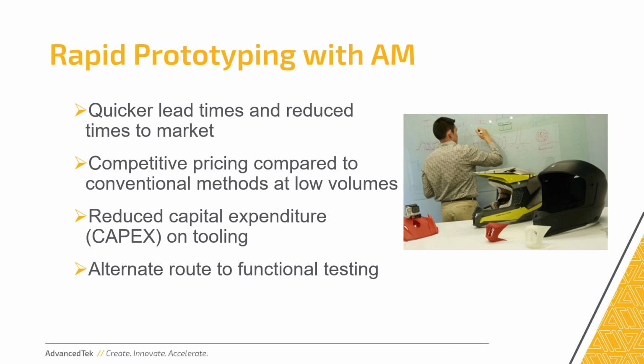And you're reducing a lot of your capital expenditure on tooling. So if you make a lot of injection molded parts, prototyping and getting a feel for those parts before you tool up can save you a lot of money in some cases. And it also allows you to do some functional testing before you get those first article pieces off the tool.